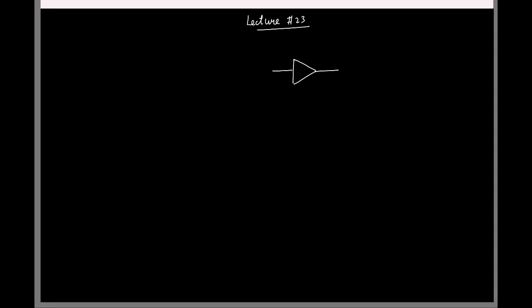And this was basically your common source amplifier, and you can increase its gain by putting cascodes, folded cascodes, and all that stuff. We also looked at the case where the amplifier takes two inputs and amplifies the difference and gives a single ended output, right? And this was our 5 transistor diff amp, and again you can do all sorts of techniques to boost its output impedance.